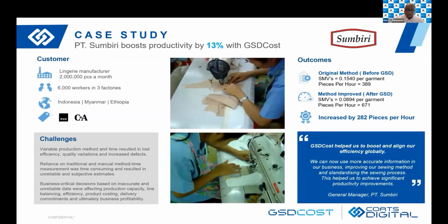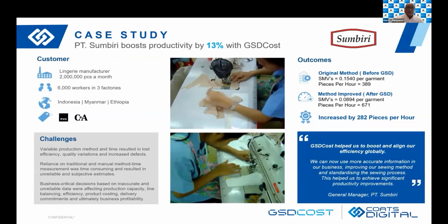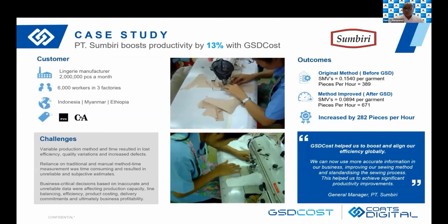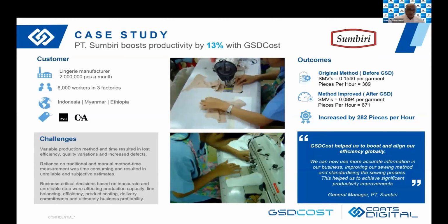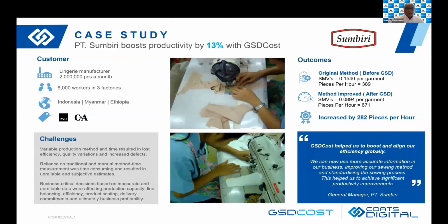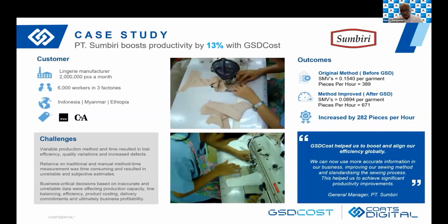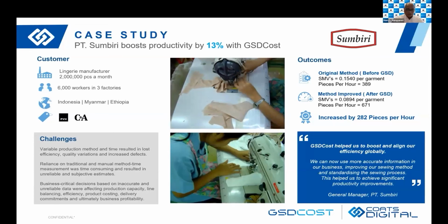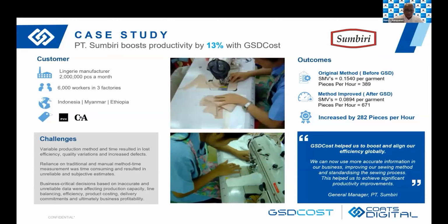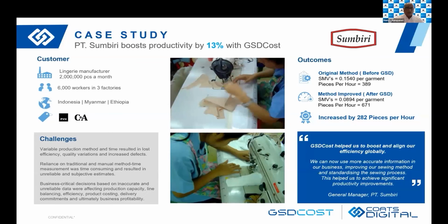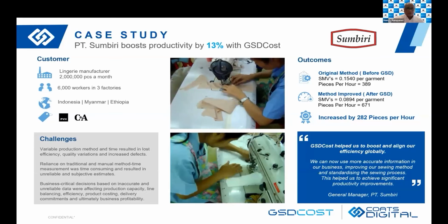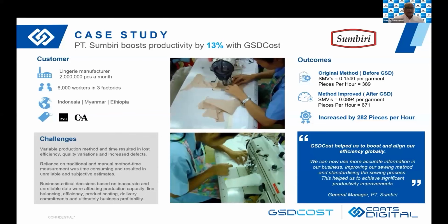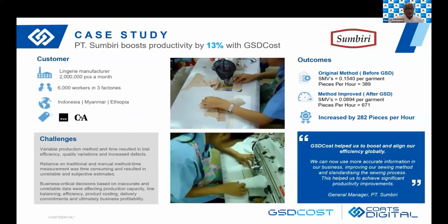So when we calculated that with the GSD as a current method, it was producing 389 pieces per hour. By just looking at the workplace layout and also requesting from the previous operation how the bundle is requested and how we needed for this operation to carry out, we replaced the bundle to the right-hand side and trained the team member to obtain and locate during the machine time.